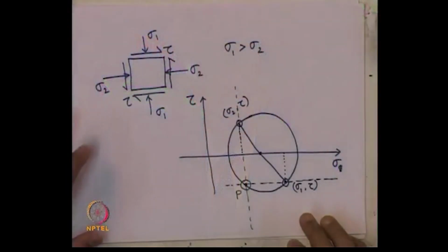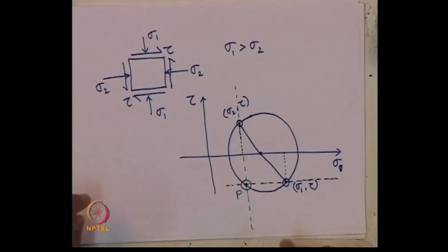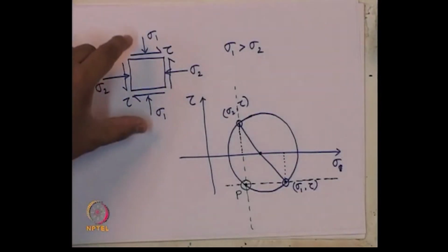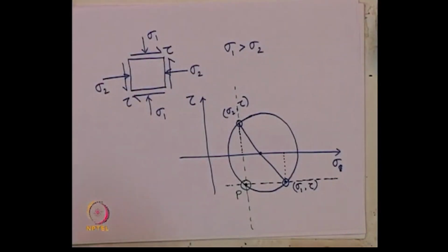Considering two dimensional stresses for soil in static problems is pretty well valid, because when we take any soil element, we consider the vertical stress as one major principal stress and the horizontal stress throughout the cross section remains uniform; we assume this in static problems.